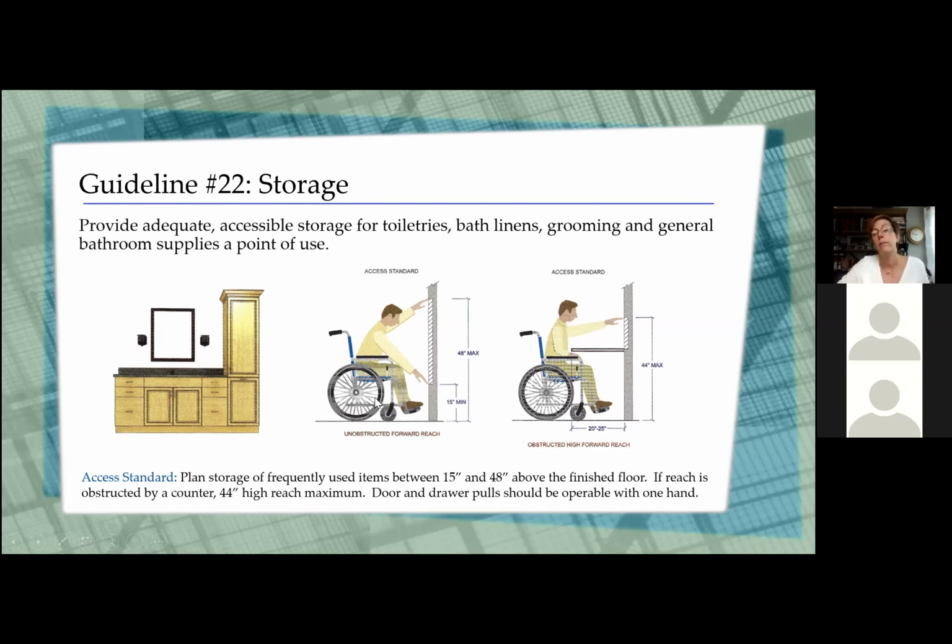When they can wheel directly up to the wall or to wherever you've got storage built in, they're really only going to be able to reach about 48 inches tall. So these linen cabinets, which are typically 84 inches, a lot of times those top shelves won't be able to be used by somebody in a wheelchair, but it's great use if you're not in a wheelchair, and you've still got plenty of storage within the bathroom itself.